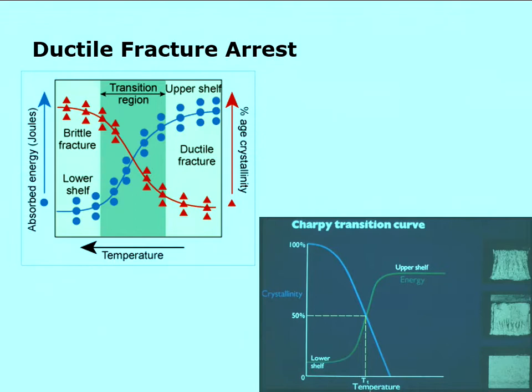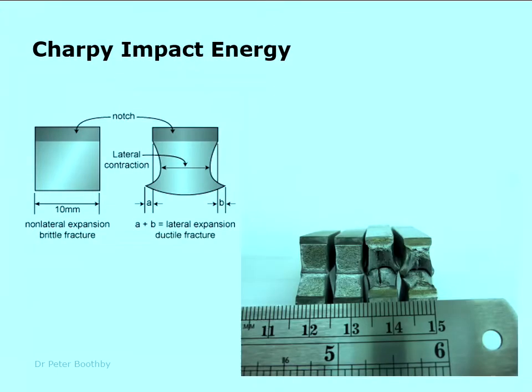Right, now fatigue life of pipelines, the concept which is included in TD1, which again I'll be asking you to apply in the assignment that we're going to start. What this is doing, first of all, there is an SN curve in there. Provided you have done a proper hydro test, you can apply that fatigue design curve.